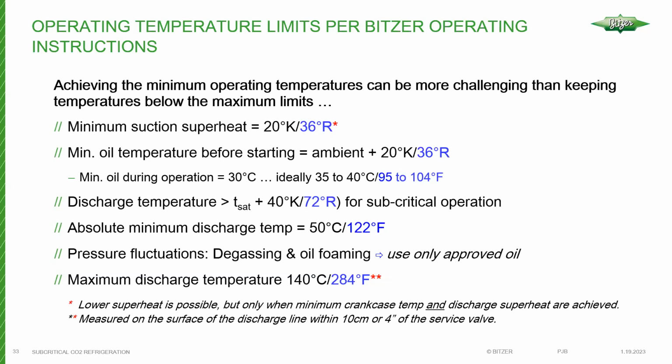Okay, so it's important to understand that you're never going to eliminate refrigerant from getting in the oil. It's going to get there no matter what. And it's a function of oil temperature, the refrigerant type, the oil type, and the refrigerant pressure. And generally speaking, the higher pressure refrigerant and the lower temperature of the oil, these two things work together to result in more and more refrigerant in the oil.